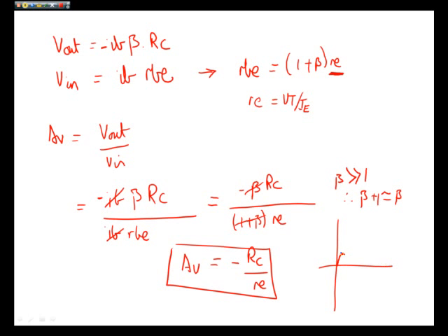That effectively means that if I was to draw our input signal like that, our output signal would be on some DC bias, and it would be 180 degrees out of phase, or inverted. In other words, multiplied by -1. So there's our Vout. It would be sat on some DC level, and that might have been our input signal Vin at 0 volts, capacitively coupled into the base, of course.